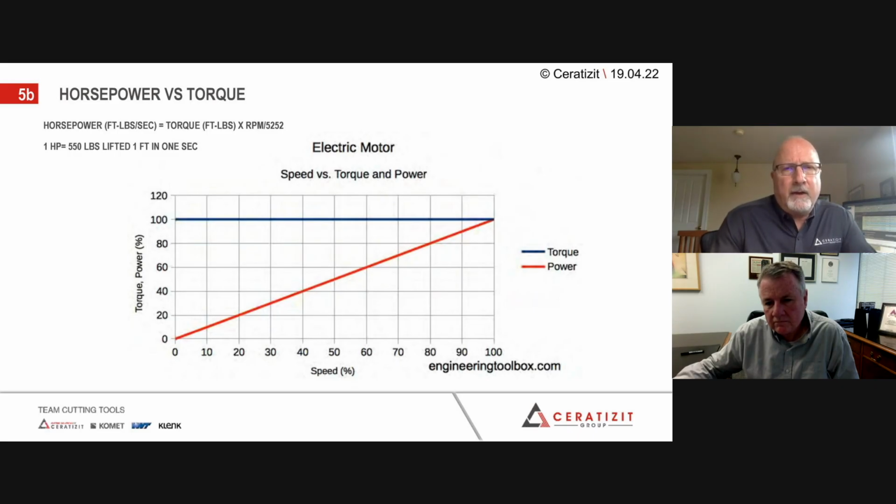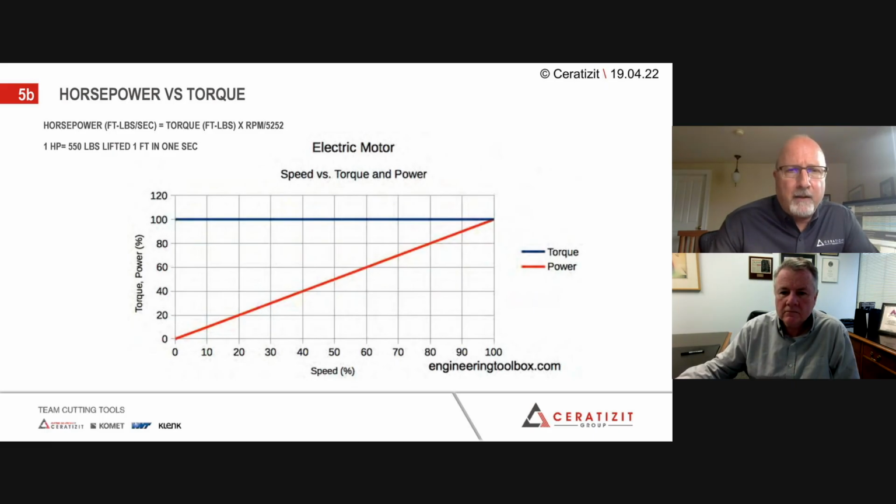Also recognize that these high feed systems have cutting forces that are mostly directed axially, up through the axis of the tool towards the spindle. So they are gentle on the spindle, but they also are not going to generate a lot of chatter. So they're very useful for long reach face milling. If you have a deep pocket and you need to get a shank style tool down in there, a high feed system is going to be very forgiving when it comes to machining that material.